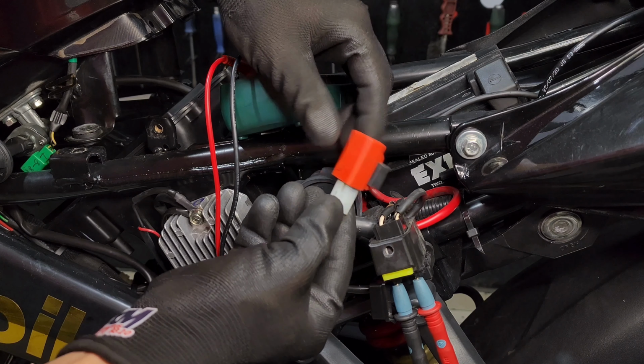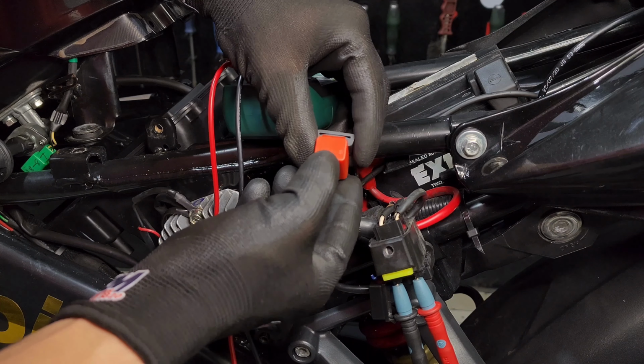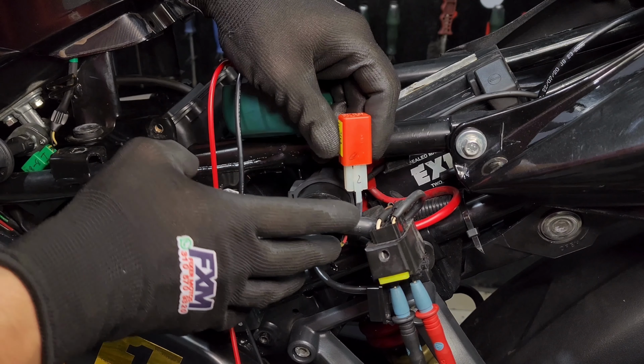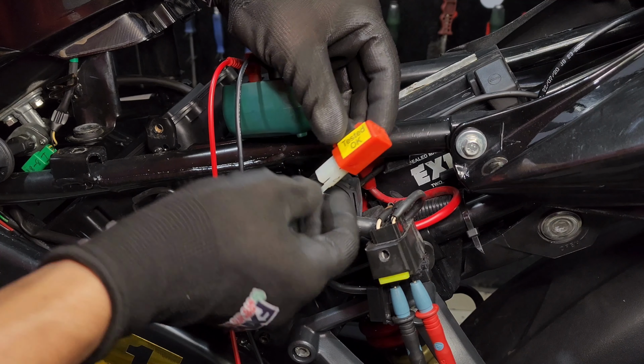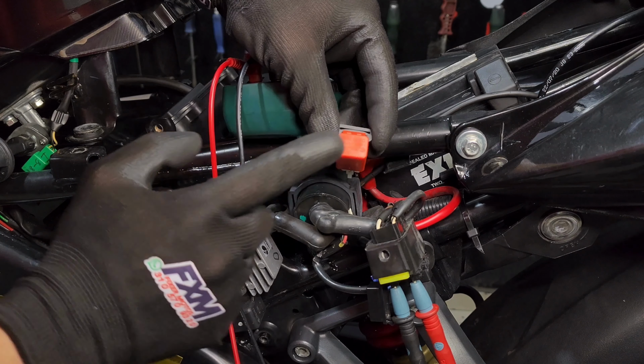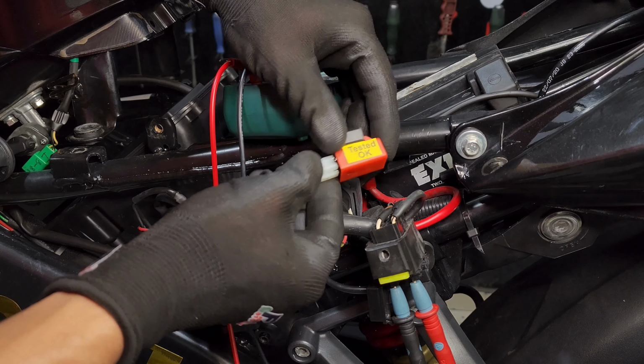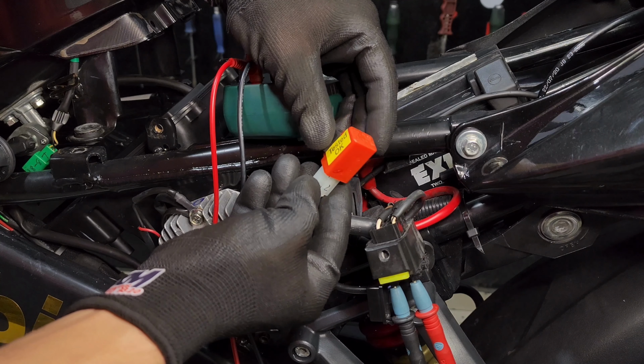This happens because the flashers are designed for specific amp consumptions. They are already designed by the manufacturer. That is why we must use original spare parts. However, other types of spare parts can be used, yes, but since the manufacturer doesn't tell us the flasher's rated load, we must calculate it.